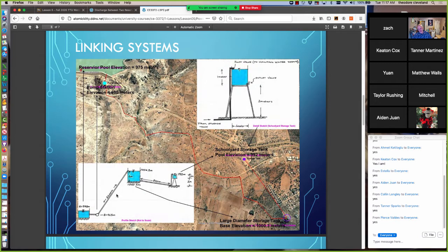From a water quality public health standpoint, we want the pipes to always have water in them. And certainly in this part of Africa, I don't think that they're going to enforce a 35 psi, but we want positive pressure in the pipes so that water has to leak out.